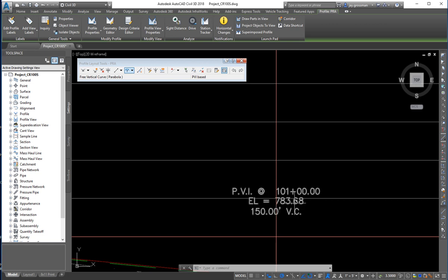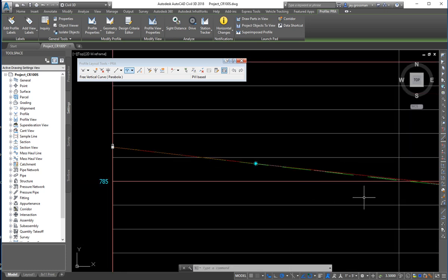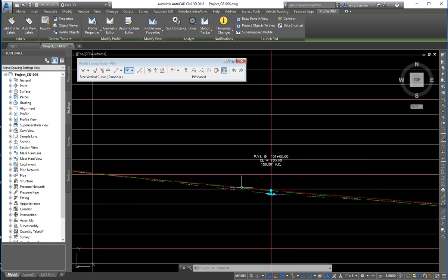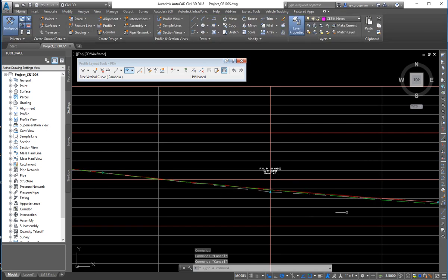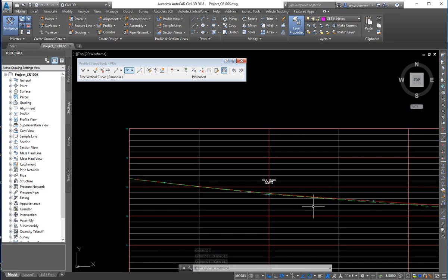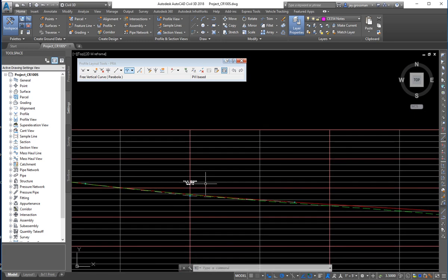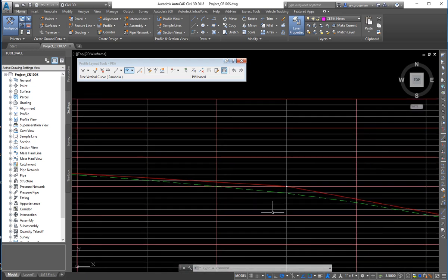The elevation will float to whatever elevation is through there, but anyway, I claim this is a pretty well done one. So nice long curve. People can see these. If you make them too short, even though it meets the required K values, it throws people off a little bit, and they just think it looks a little chintzy.